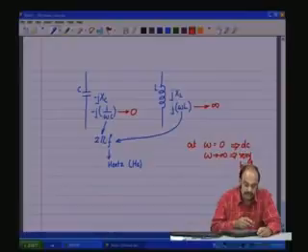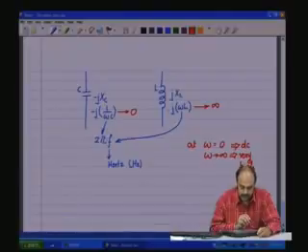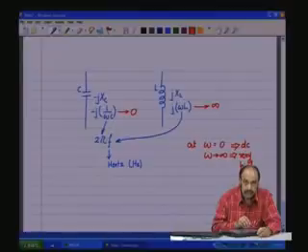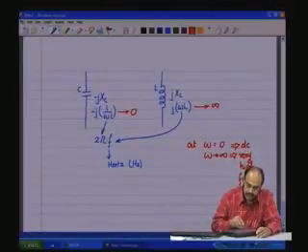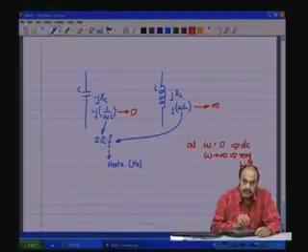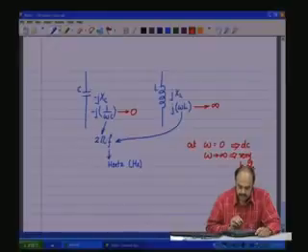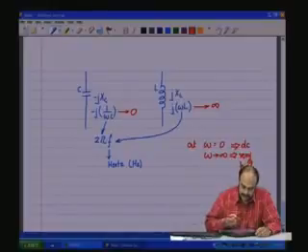On the lower frequency side, the inductor is going to pass the low frequencies, whereas the capacitor provides a high impedance at low frequencies, which means it is not going to pass low frequencies. This is one of the important features that one can learn by studying the steady state character.